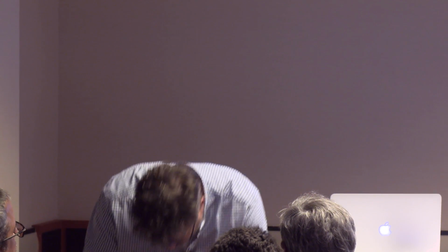But I don't even think I've ever. Layout, your dimensions are set to. Well, in Layout, if it's an architectural thing, it's usually a 16th. If it's a shop drawing, if it's a compound roof, and I'm doing like a valley, I'll set it to 30 seconds. And I'll be damned if there's a guy out there that's actually ever looked and done a 30-second. I would like to know that they are, but if I'm pulling dimensions on something complicated like that, I'll do a 30-second, or if it's a smaller piece, but typically no tighter than that.